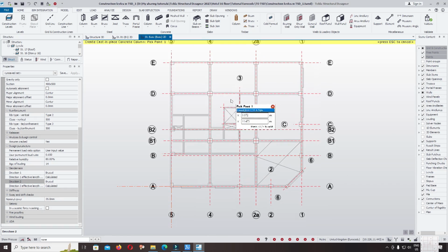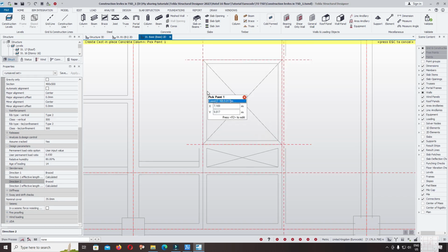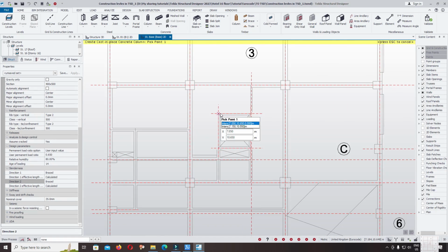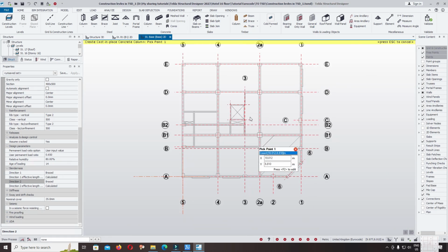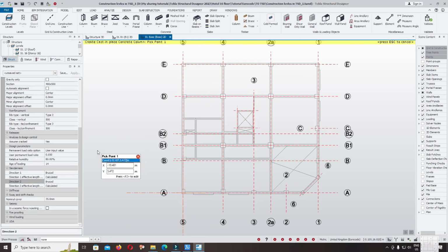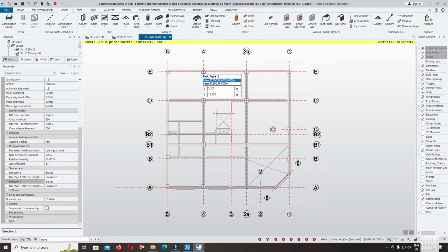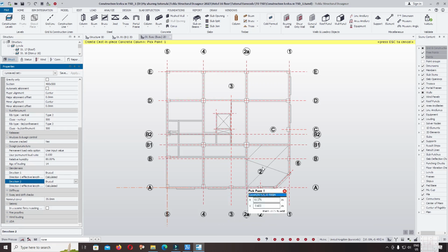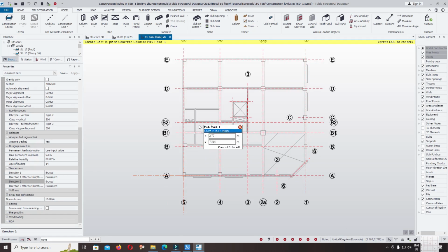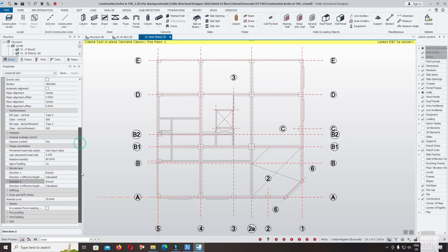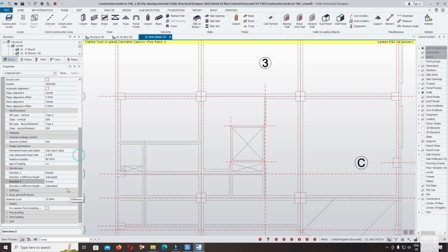In our structure we design the column and beam, and we have only one core wall, and the building is 17 stories high, so maybe it affects the column. Some columns can be non-sway and some columns can be sway. It is difficult to assume all the columns are non-sway or sway, so we must check alpha critical. In case you add more walls in both directions, on grid line 5, grid line E, grid line A and grid line 1, then this structure can maybe be assumed as a non-sway frame column. You can keep the default braced column.